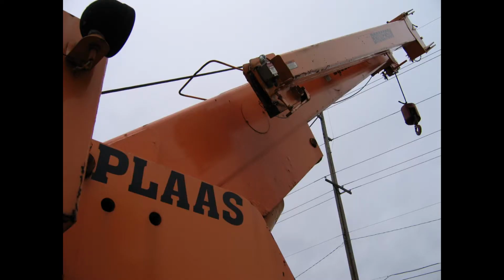Hoist areas. In all situations where equipment and material hoisting operations take place, we will protect our employees from fall hazards. When we are involved in hoisting operations, we will use the following fall protection systems at these specific locations. When operations require the materials to be lifted by crane to a landing zone and do not require an employee to lean through the access opening or out of the edge to receive or guide materials, we will use fall arrest equipment or a guardrail system.